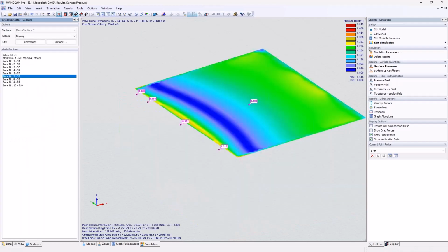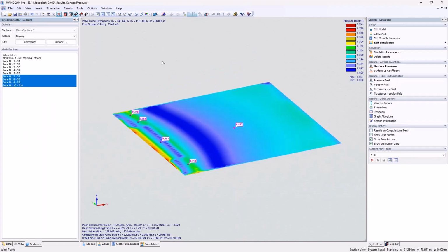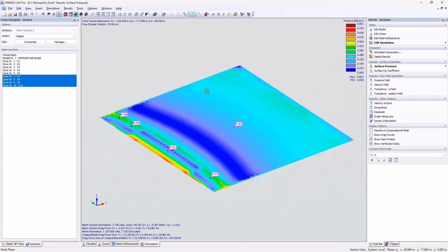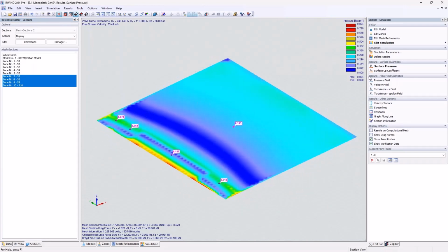Let me quickly restrict our zones only to the roof. You can usually do that in the section tab. Then we can see that the dark blue would be a difference of 0 most likely, and the further away we are, the bigger the difference will be. But of course, the standard does not really take into account a finer determination of an area. So we might have some bigger differences to the standard.